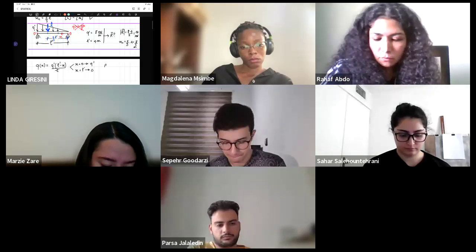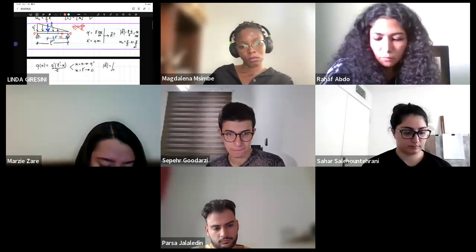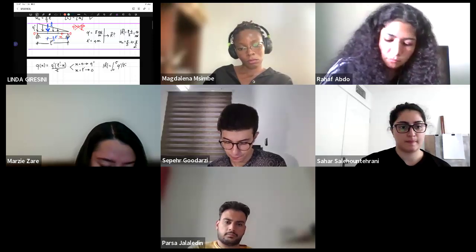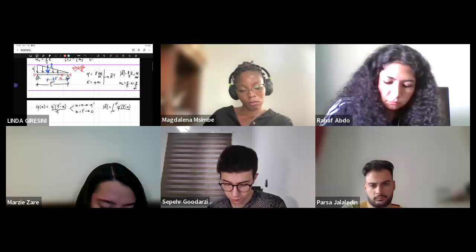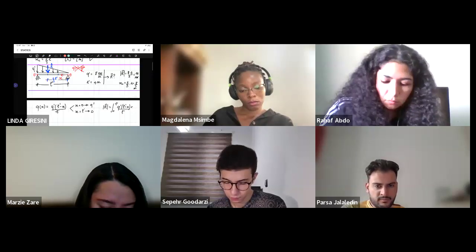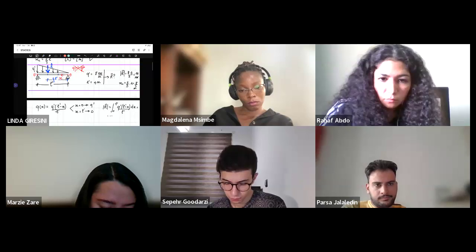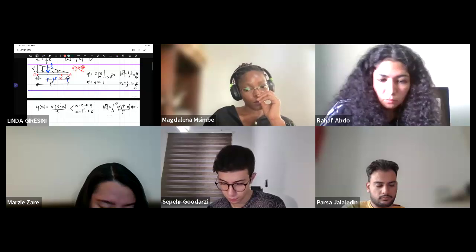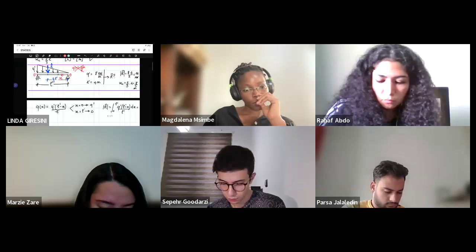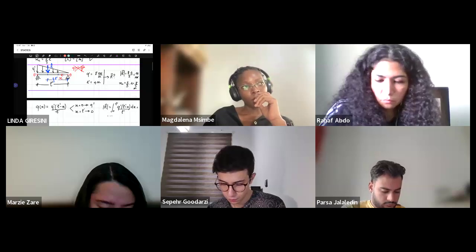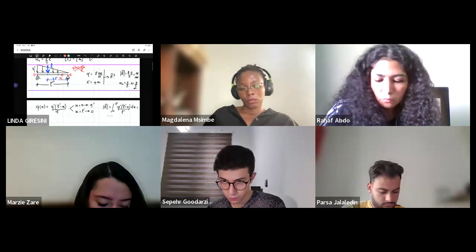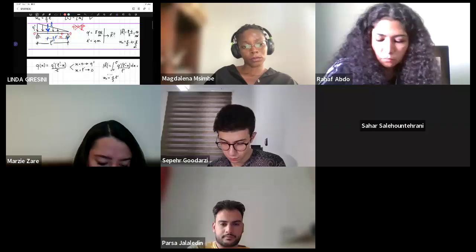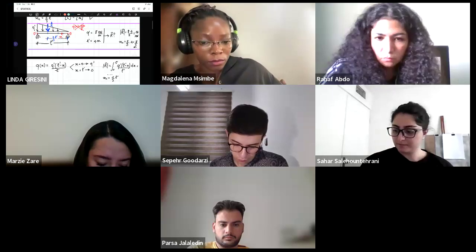So as a function, then you'll have to write, for example, the integral from 0 to L first of Q first times (L first minus x) divided by L first dx, equal to blah, blah, blah. And you'll have the same result. You can check it if you want. The result will be 1/3. So xc in this case will be 1/3 of L first instead of 2/3.